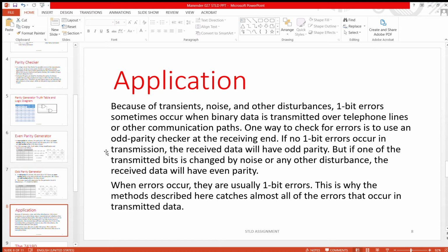In digital electronic systems, during data transmission and processing, data usually gets distorted. This is due to the noises added to it. Such noises change zeros to ones and ones to zeros. It is necessary to identify and remove these errors because if we don't, then the data which gets transmitted won't be correct. One of the most widely used error detection techniques for the transmission of data and for sharing of information between devices is called parity checking.